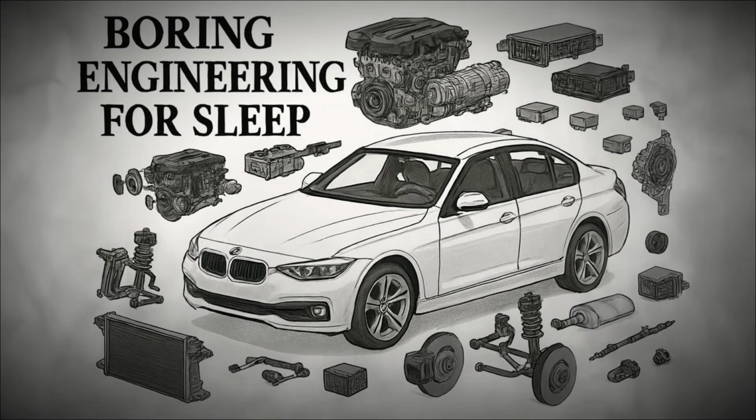When the driver turns the key or presses the start button, current flows from the battery through a solenoid to the starter motor. The solenoid also pushes a small gear on the starter shaft into contact with the flywheel, and as the motor spins, it turns the engine over until it can run on its own power. Once the engine starts, the starter gear disengages automatically.